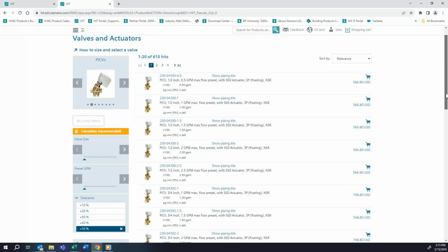When I'm talking about selection: size of the valve, the gallons per minute, GPM, of the valve, the BTU required in the design for the application that would host this valve, the delta T, the temperature difference in and out of your coil, for instance, or from the beginning of the loop to the end of the loop. All of these are features that are necessary in the selection.